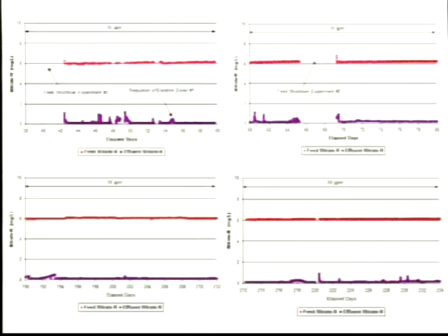And one of the things you have to understand about biological systems is when you shut them down for 4 or 5 days, if you've just started the system up, and David had referred to this earlier, if you have a clean system, it's going to take time to start back up. But if you've got a system that has microbes that have been growing for 30 to 40 days and the system's starting to really acclimate, shutting it down for a week and then restarting it, you're going to see a minimal amount of breakthrough of that nitrate. Shutting it down for months on end and then restarting it, you may eventually see some breakthrough when you restart it.